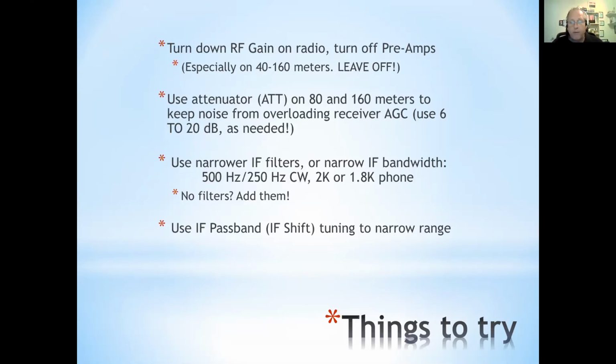And we're going to talk about how that works in a second. But I can't tell you, except for the volume control and the RF gain control, the IF passband control on my HF radios is the one that I use absolutely the most, to try to get rid of interference signals and try to narrow the bandwidth down on one side to get rid of a noise source that's on another side.